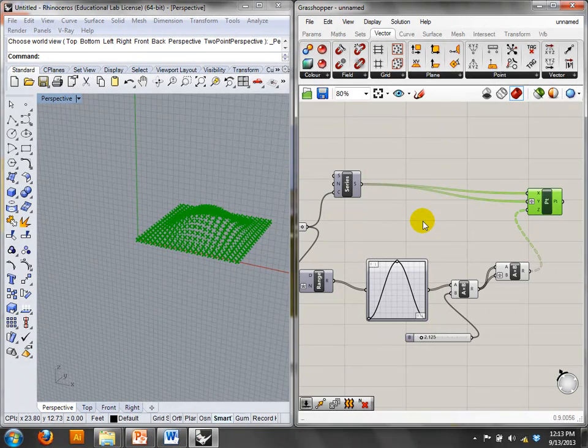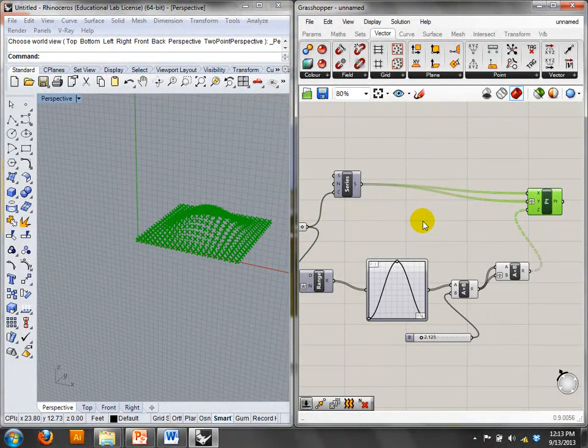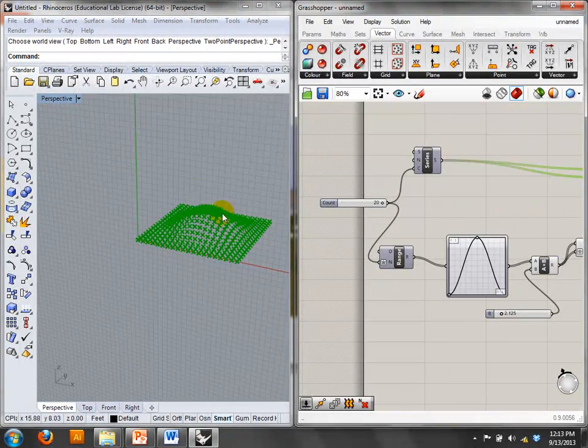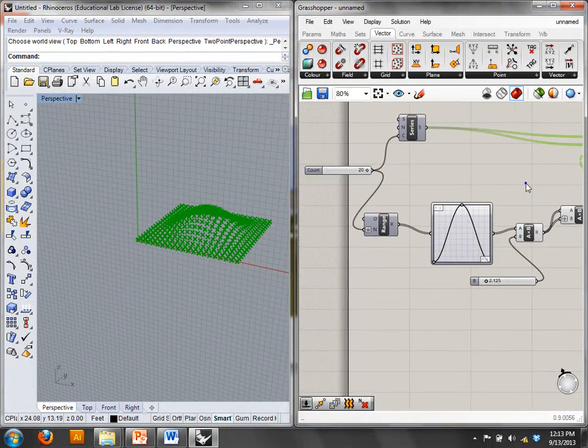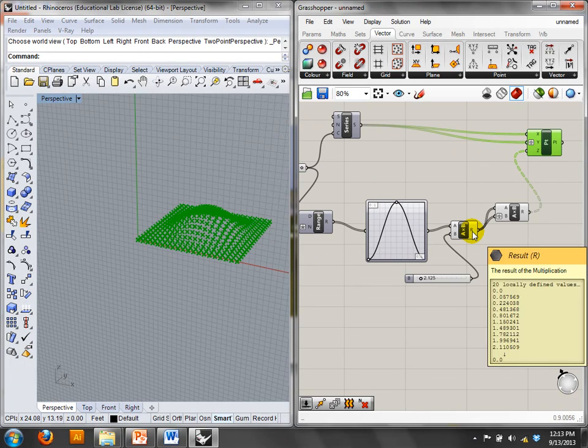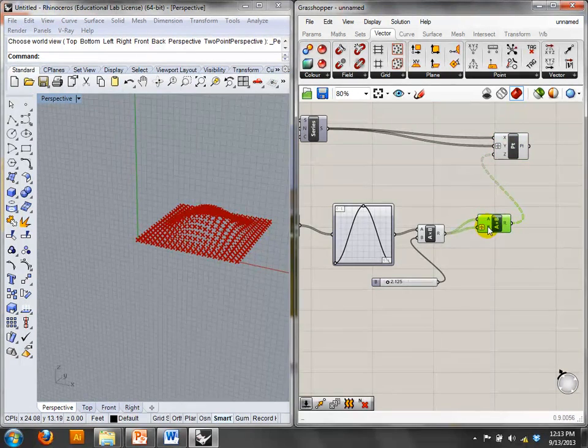This is just like what you guys did. I think in your example it was a wall, okay? It's just a grid of points, x and y. I grafted the y to get the grid. The z is actually what we're changing, right? It's where the points are being disturbed, up and down. And so for the z, I made a graph mapper, like a paraboloid. I multiplied it because you need to multiply it, otherwise it's going to be flat, basically.